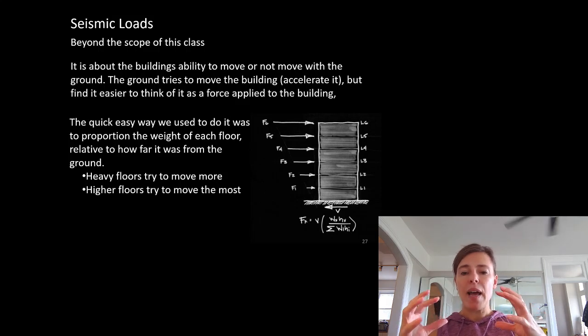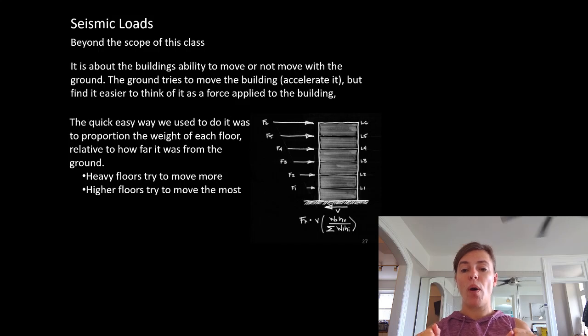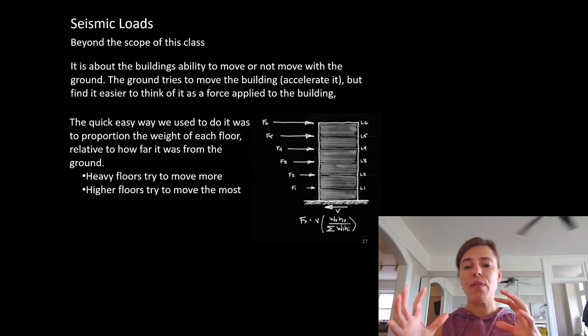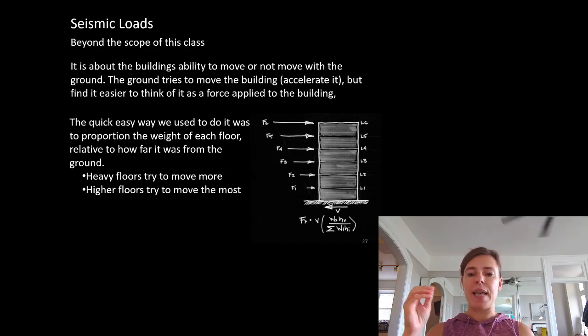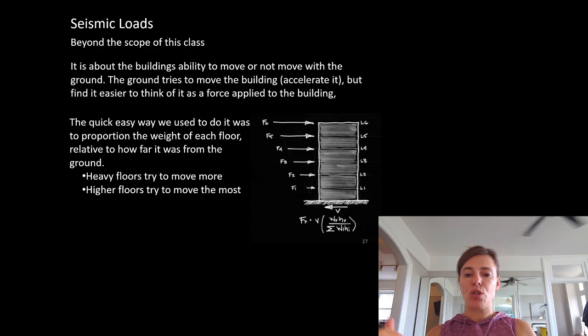And instead of saying, how much is the ground trying to move, what we say is, what's the acceleration of the ground? Or how much is that ground going to try to drag the building instead? So instead of looking at it in that way, we say, okay, what is the amount the ground can move, but apply it as a load at each story of our building.